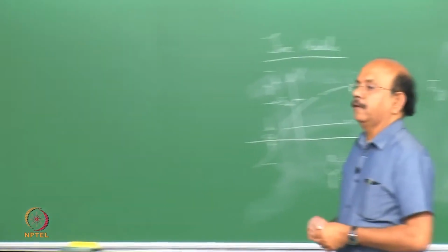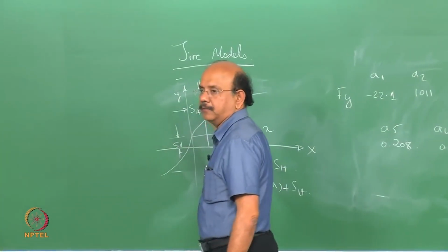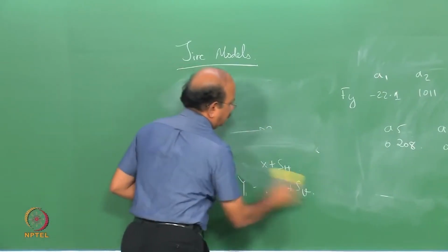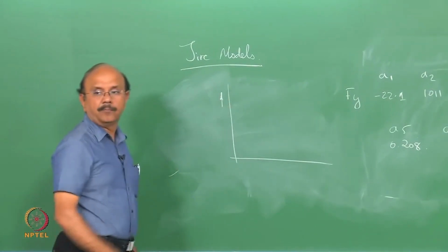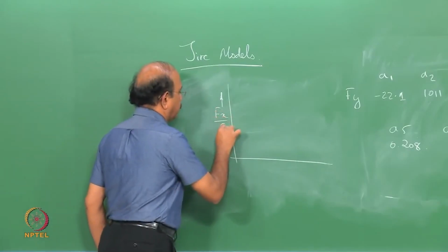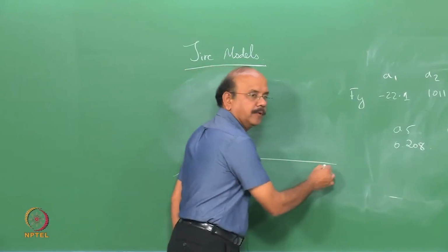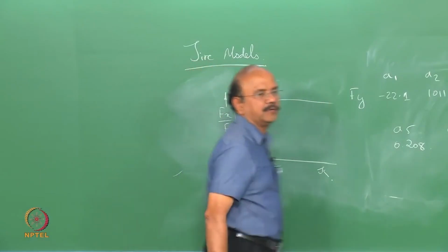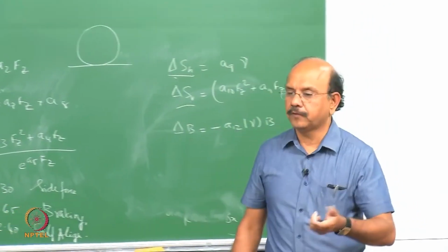Effects with mu, would the curve be the same? No, because it would depend on, well, to a certain extent, it's a good question. That's why people in those days used to normalize this curve and then plot Fx by Fz, and then have the kappa value, and they say that this normalized curve is fine. But this brings out a very important topic on friction itself, the friction coefficient itself.